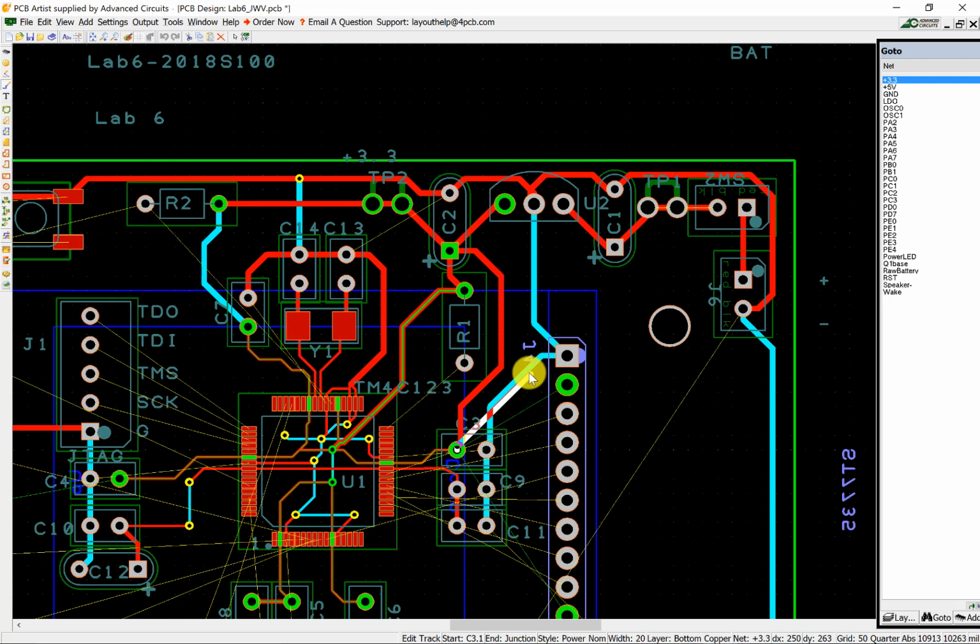If I double the bus speed, how much more power does it take? The voltage is constant. Power is voltage times current. So if I double the bus speed, how much more current do I have? The answer is double. I'll prove it to you someday if you want.